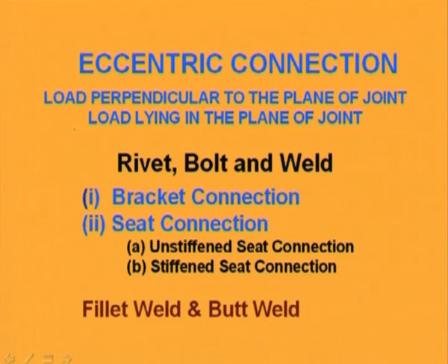If it is riveted, accordingly we have to decide whether bolted or welded. Again, weld connections means whether it is butt weld or fillet weld, that also we have to think about and accordingly design. So as per the requirement, as per the situation demands, as per the availability, we have to decide whether we will go for rivet, bolt or welded joint, and again whether fillet weld or butt weld in case of a welded joint.